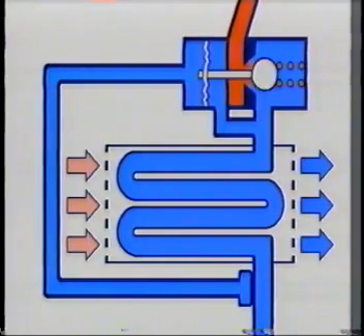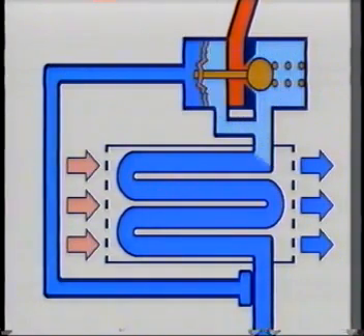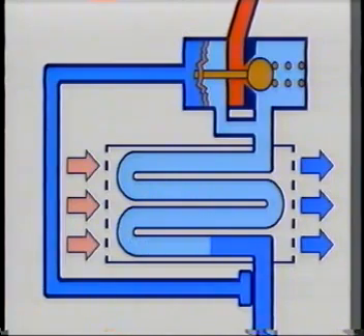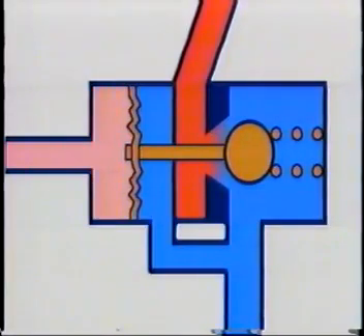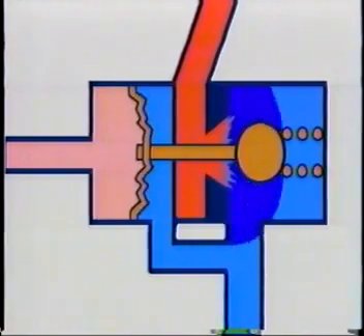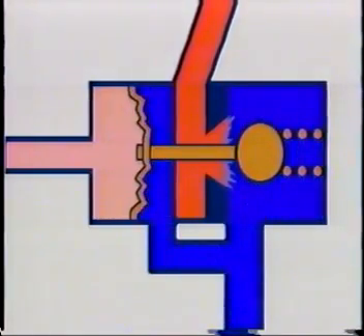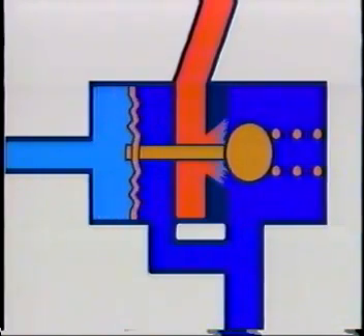And the expansion valve reduces the valve passage accordingly so that a smaller amount of refrigerant is allowed to flow through the system. The expansion valve increases and decreases the valve passage repeatedly in this way so that an appropriate amount of refrigerant is supplied at all times.